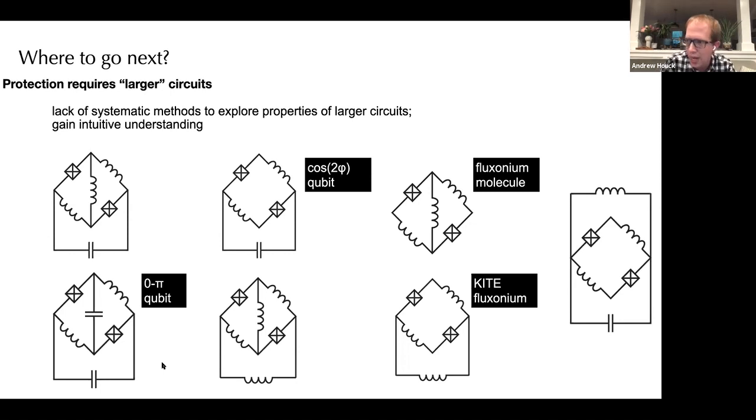Although we've tried quite a few qubits over the 20 years that we've had superconducting qubits, the primary trajectory of qubits includes essentially a Cooper pair box, which is a lone Josephson junction; the Transmon qubit, which is a Josephson junction shunted by a capacitor; the Fluxonium qubit, which is a Josephson junction shunted by an inductor; and the newest qubit, heavy Fluxonium, which is a Josephson junction simultaneously shunted by a capacitor and an inductor.